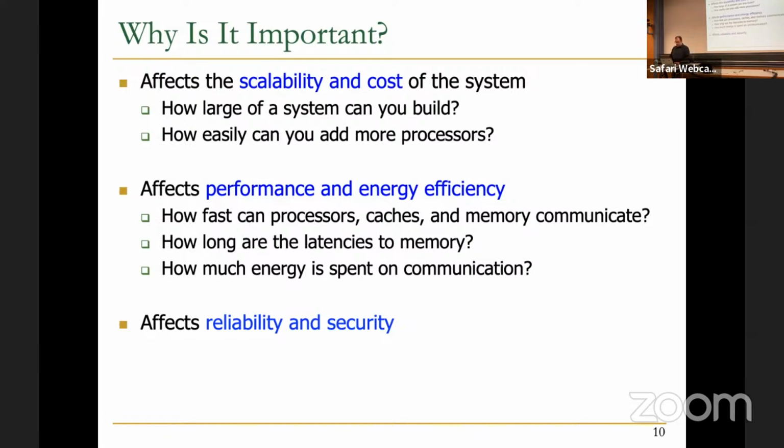But at the same time, interconnect can also cause security issues. Interconnect is a shared fabric across different cores. And whenever you are accessing a cache, for example, your message to that cache bank can actually be observed by other cores as well, because you have a shared medium here. And people have worked a lot to use that interconnect as a side channel so that they can leak information.